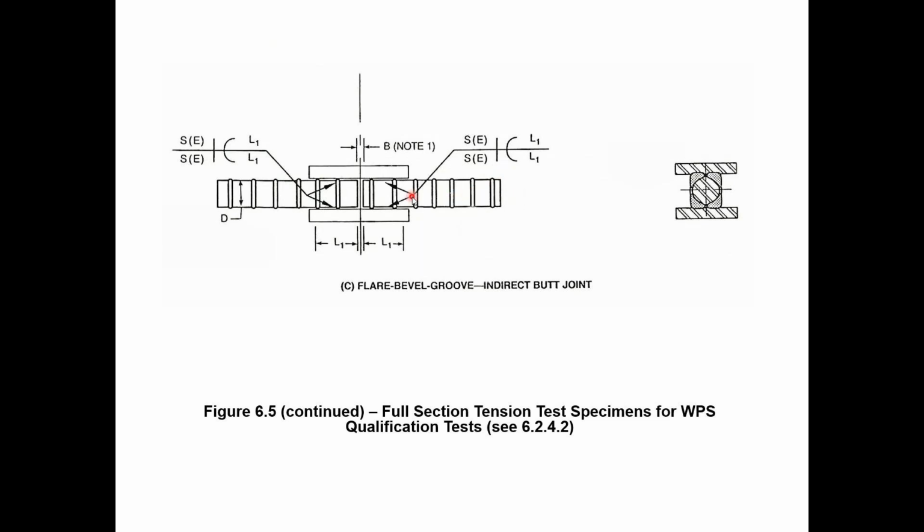This is another example of what one of those might look like. So you've got two bars coming together as a butt connection, but instead of just a butt weld, they've actually got these splice plates that are lapped over the two different pieces of rebar to keep you from having to do a direct full penetration butt weld. So you see in section, that's really what this looks like. You end up with 1, 2, 3, 4 flare bevel welds.